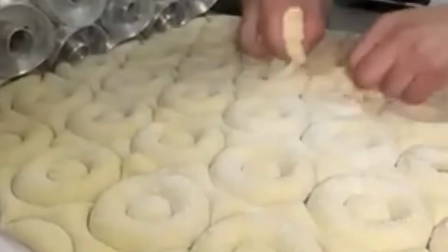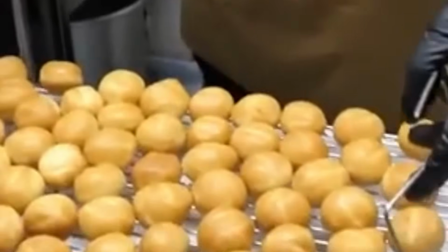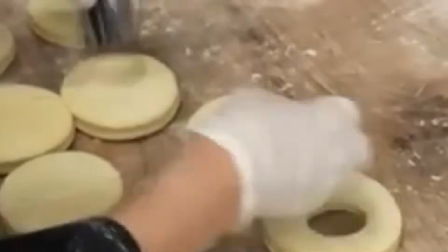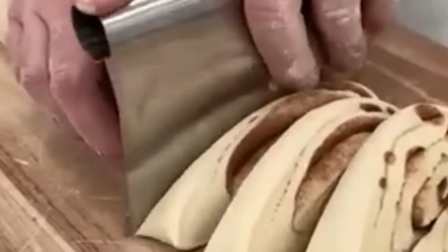This conveyor feeds a volumetric divider equipped with servo-driven pistons that portion dough into uniform units. Each portion is shaped into a ball using a rotary rounder. Rounded dough balls are transported by a belt conveyor into a multi-level proofer cabinet. Inside the cabinet, humidity and temperature are controlled to activate yeast fermentation. The dough rests for 30 to 60 minutes based on size and environmental conditions.